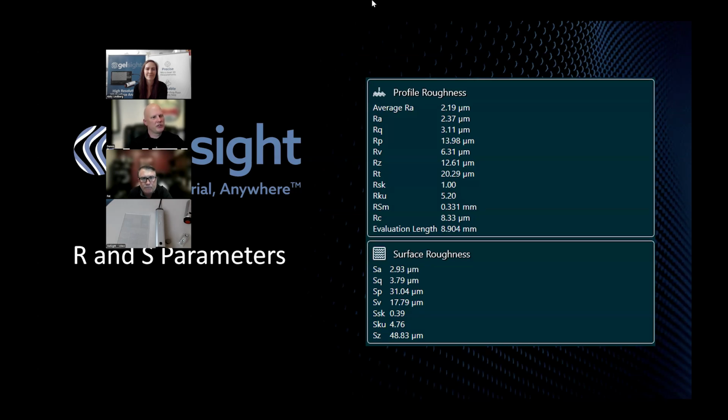One of the interesting things we see, we talk about additive a lot for roughness here at GelSight because additive companies have been some of our earliest adopters. And that bigger field of view with additive components tends to mean they buy the mobile instead of the GelSight Max. So the GelSight Max is the system extremely finely tuned for measuring roughness down to the 0.2 micron level, which we are doing today with several companies making very high resolution parts and many more of those to come, especially medical and other types of measurement challenges that we solve in a unique way.